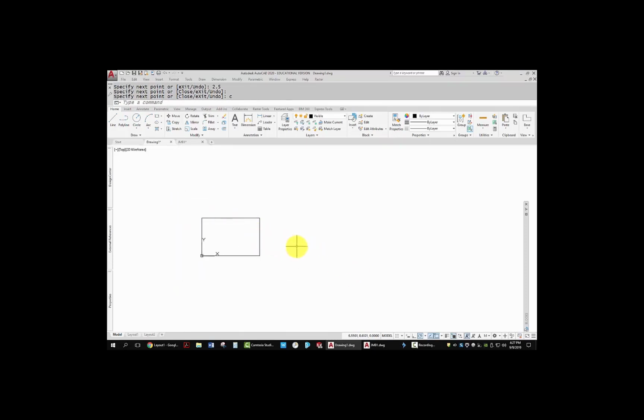This is something I drew with lines. If I were to use P lines, I'm going to hover over that corner, go over 2 inches so that the spacing between the two views is 2 inches. Go over 2.25, go up until it's level with the top, go to the left by 0.5, go straight down by 2. I'm going to come over until it lines up with the beginning. C for close. In this case, I have a closed P line. If I turn line weights on, because I'm on the visible layer, these lines are thick. I'm going to turn them off for right now.